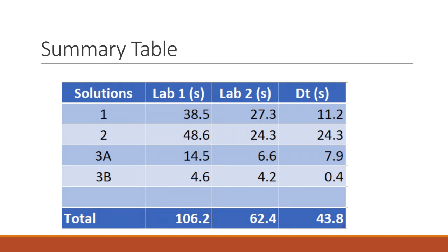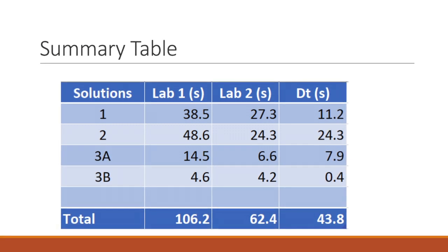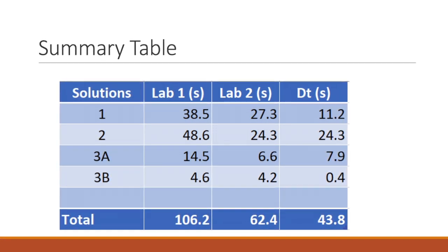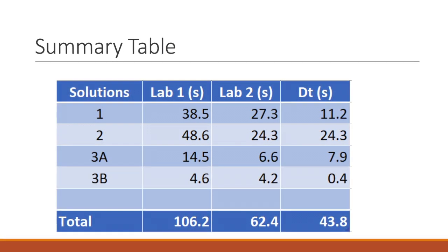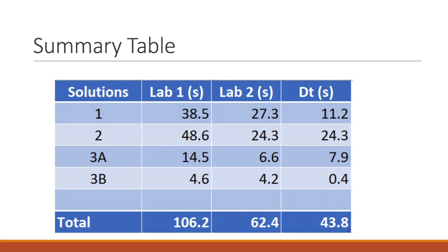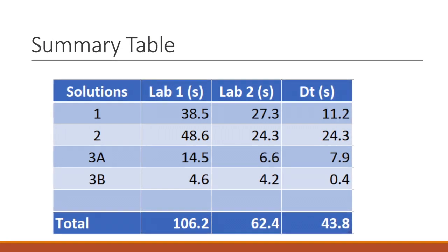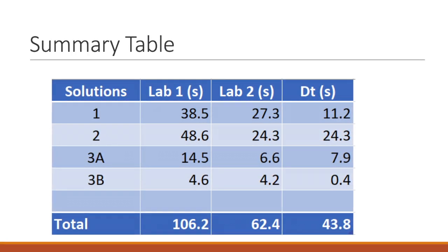In summary, for our first problem, we started with a time of 38.5 seconds, and after implementing our solution, we could reduce our time by 11.2 seconds to a final time of 27.3 seconds. Our second issue had an initial time of 48.6 seconds, and after implementing the electric drill, we could reduce the workstation cycle time and combine two workstations together to a time of 24.3 seconds. The last